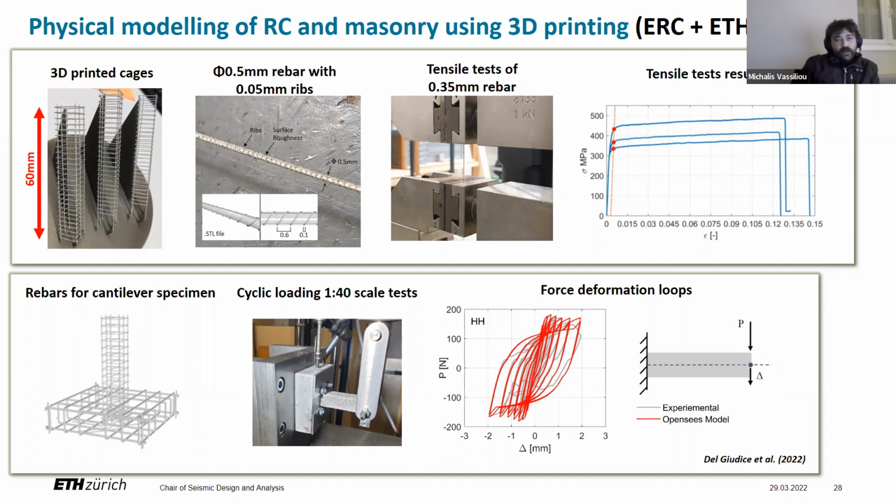Some results that we got, but we have already fixed this, but I do not have the formal results yet. Here is the stress-strain relation of the material of the rebar. You see that there is some pretty large dispersion over here. I mean, the strength of the 3D printed steel is close to what you would be expecting for rebars, but the dispersion is larger.